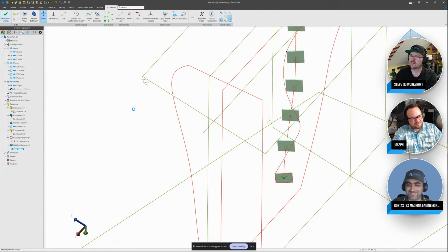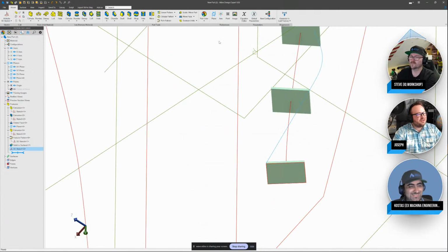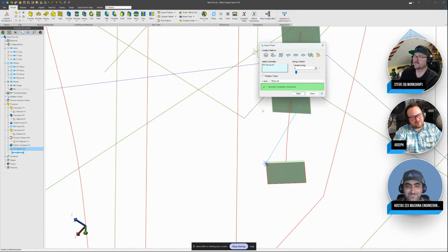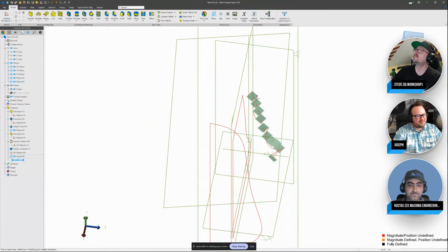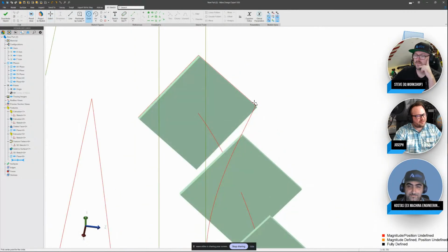Now, I don't know if we want to see the whole thing or not, because you're just watching me be clicking corners 4 times in a row. But if I deactivate my sketch, create a plane again right at the beginning of this 3D path, and activate a 2D sketch on the plane that we just created, I can make our sweep cross section. Of course, just one.